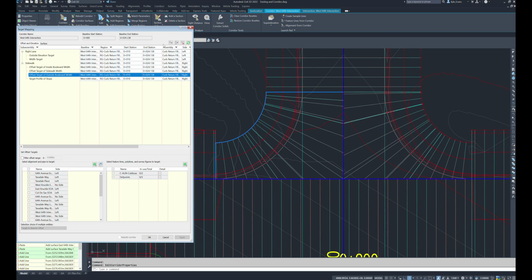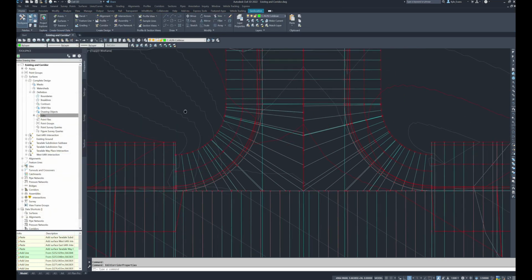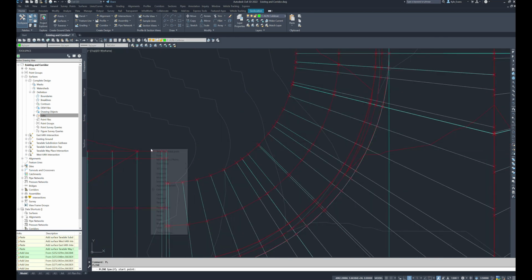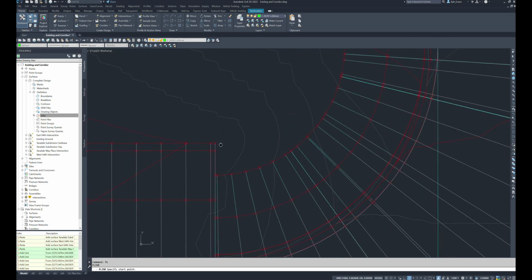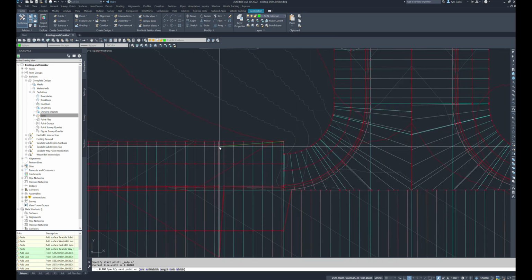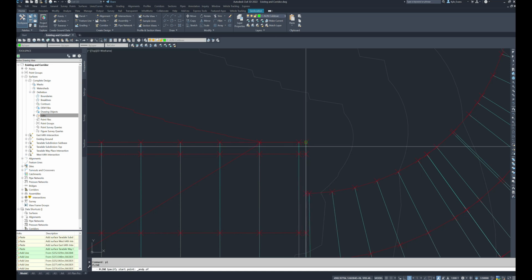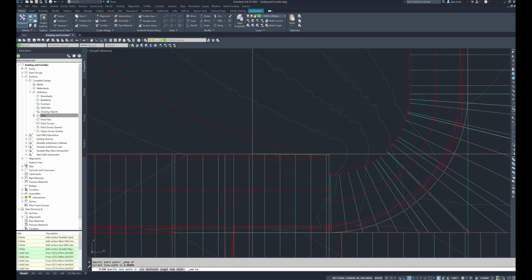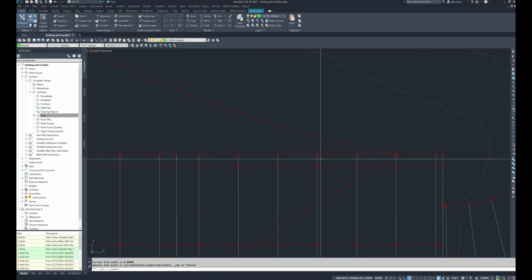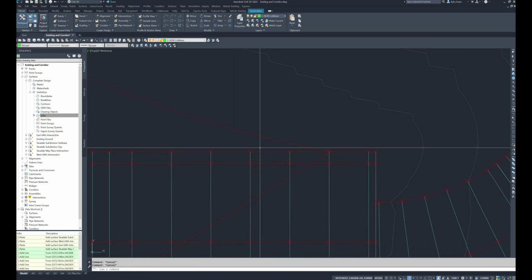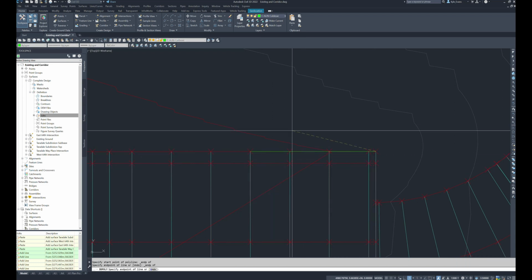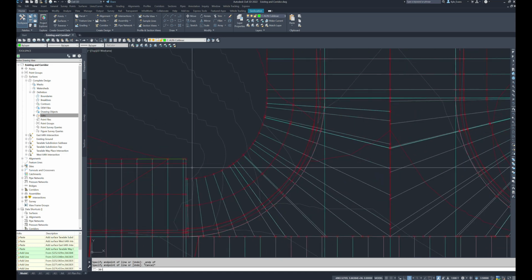So if that's the case, I'm going to try it with a feature line. We'll try it with a feature line right now to try and make the pieces match up. And essentially what I want to do is, in my city here, they like to chamfer the corners. So I'm going to draw just a polyline. Okay, we're going to try a 3D poly since it's not letting me snap. Okay, 3D poly works. Now 3D poly might not work for the chamfer command itself.